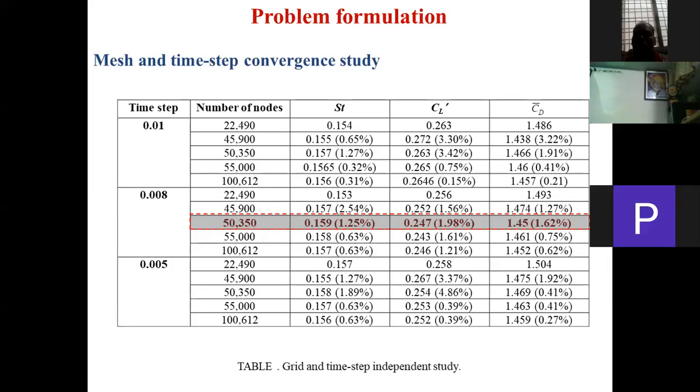Now, once you model your problem, you have done the discretization, meshing and grid-independence study. Now, to be confident that my results are right, what we do is compare these results with some earlier published work or some experimental work. What is the beauty of CFD nowadays?